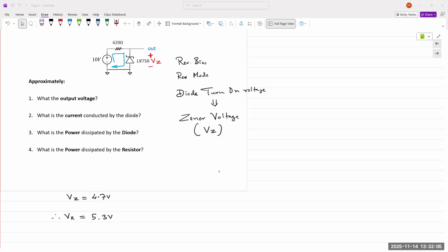We increase the supply voltage from 0 to 0.5. Diode might start conducting just a little bit. This is in forward bias. Once it crosses 0.5, 0.6, 0.7, 0.8, diode turns on completely or fully turns on. Current starts flowing through the diode, through the circuit. Current increases, right? Now, if we increase the supply voltage from 1 volt, 2 volts, 3 volts, 4 volts, what happens? Power supply resistor is linear. You increase the voltage, current would increase. So current to the diode will also increase correspondingly.